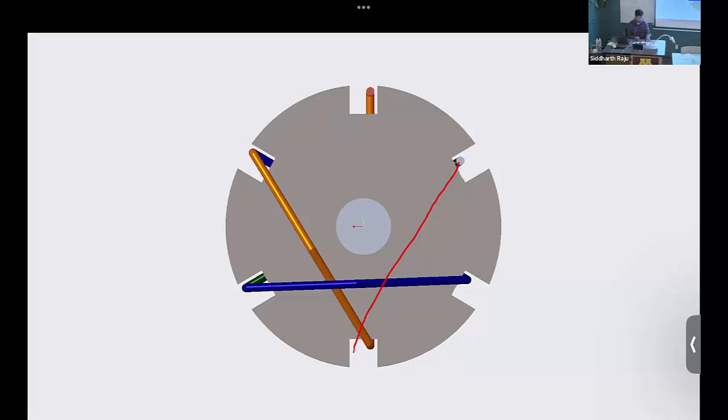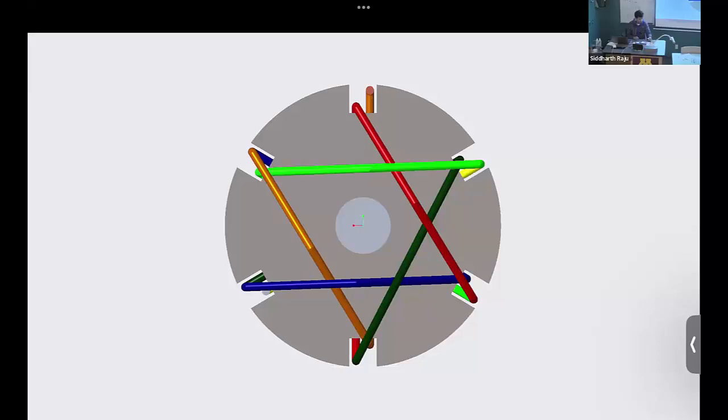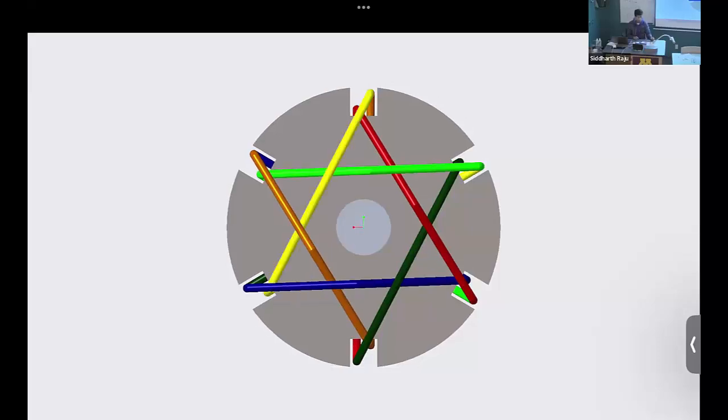But you can't terminate this wire though, because this is actually going down. This wire came out, this wire is going in, so you can't terminate them because there is no open wire here. So again, what I do is I take this conductor inwards and bring it out of this conductor. And I keep doing this again and again until the starting wire and the ending wire can touch each other, right? In which case I short them and close it out. So I do this again, and we'll end up winding it up.